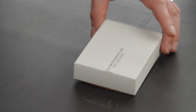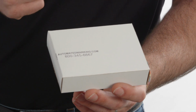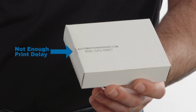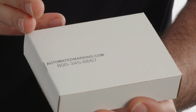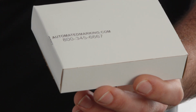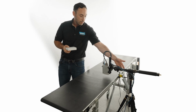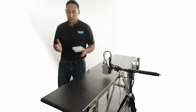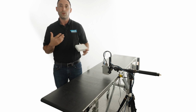Okay, so now you can see what's happened is that the print has moved to the front edge of the box because we decreased that delay. And you can see it cut the whole QR code off, and now you're just left with the text. So decreasing the delay is gonna bring you closer to the front edge, and increasing the delay is gonna bring you closer or off the back edge. So the sweet spot you're gonna wanna find is right in the middle of the package. When you go in the beginning, you're gonna wanna measure from the photo eye here to the print head, and that's gonna give you roughly the idea of when that photo eye is gonna trigger versus when the printer starts printing, and then you can fine tune from there.